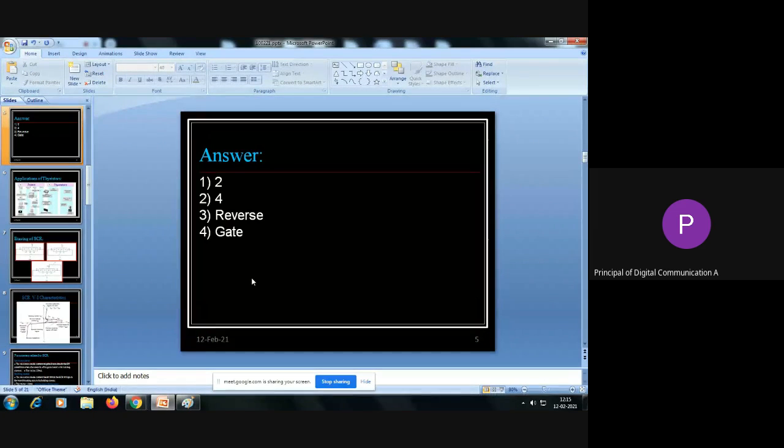The normal way to turn it on, there are two ways. Then it is a 4 layer device, and when it is in reverse mode, at that time J1 and J3 junctions are in reverse bias, and the gate is the pin which can control the SCR. How is it going to be controlled? Because SCR stands for silicon controlled rectifier. So what is rectification? It is just transforming or converting AC into DC.